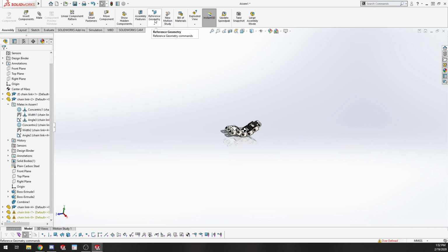But a couple of other nice things that we can do is we can make our own reference geometry. So if we have our origin on our chassis, we might want to make a plane that's the ground to measure stuff off of. We can make a new plane, add that in there, and then measure from there. We can do the same thing with coordinate systems.